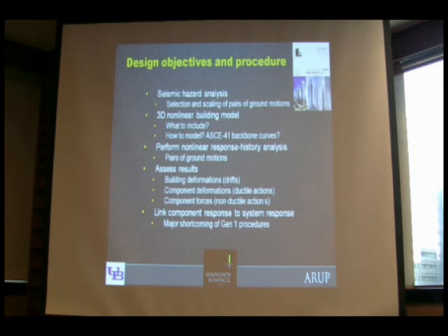So let's say you have 100 beams in a building, to pick a number, and 99 of those beams have performance that would be consistent with life safety. One of those beams has performance, rotation, associated with collapse prevention. Then the system performance is linked to component performance, and we would say that that building is in the collapse prevention performance level.